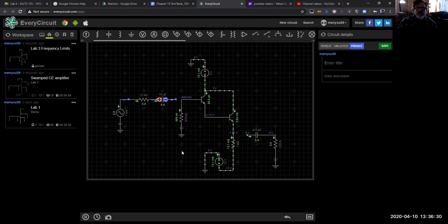And in this case, we do. So we know this transistor's activated, this transistor's activated. You can tell, we get the base tied to ground here, so we got the negative feedback activating this guy, coming in, swinging around, and going back to ground. So we do have current flow.